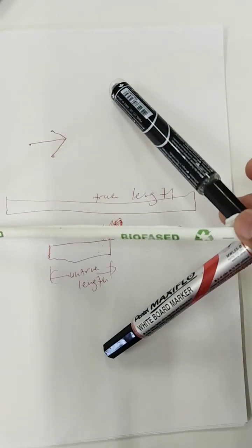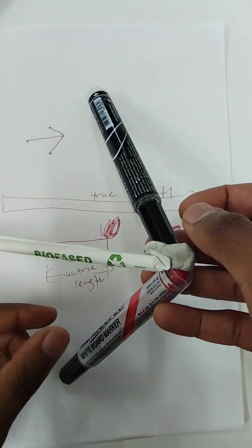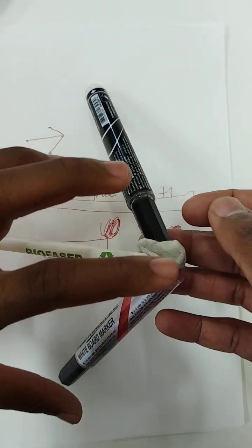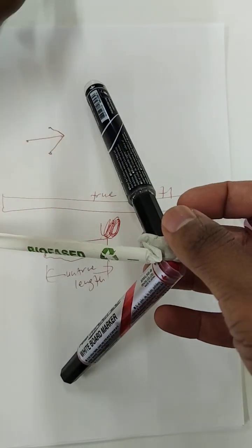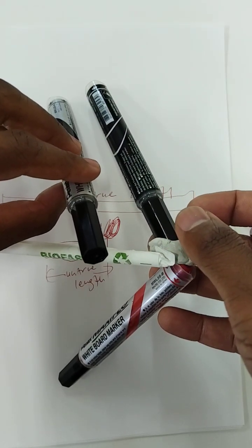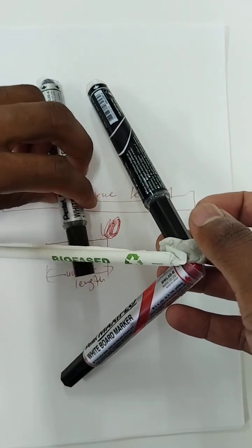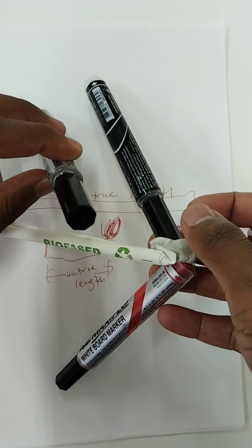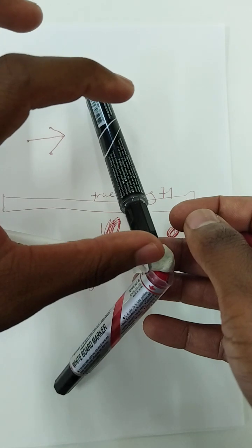This is the top view. It's straight, it's fine. But this marker and this marker, the length of these two markers, since they are at an angle like this. Okay, if this thing stands like this, you won't see the true length. For you to see the true length, we have to put this thing down. So as this thing goes up by an angle, the length of this marker gets shortened by the view. So meaning that the actual length of this marker is not this size.